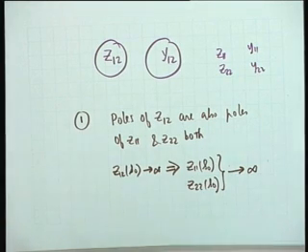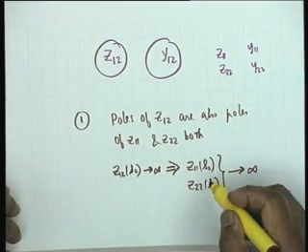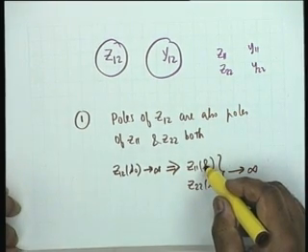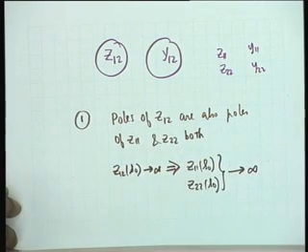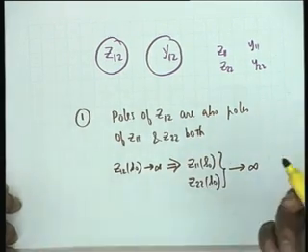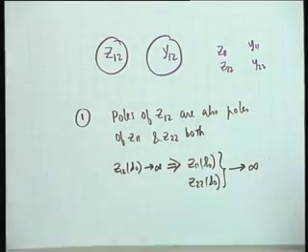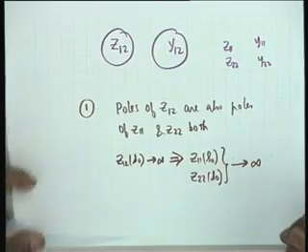The question at this point is, if z11 has a pole, does it have to be shared by z22? No. It suffices to make a counter example. If z11 has a pole, it does not necessarily have to be shared with z12. That is, the reverse is not necessarily true. But also z22. z11 and z22 can have poles which are independent of each other and independent of z12. One counter example will suffice to prove this.